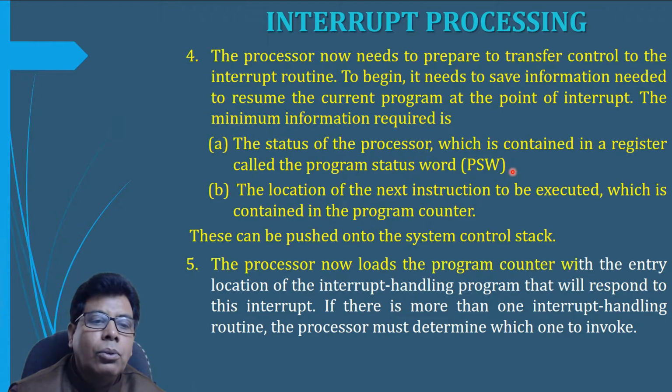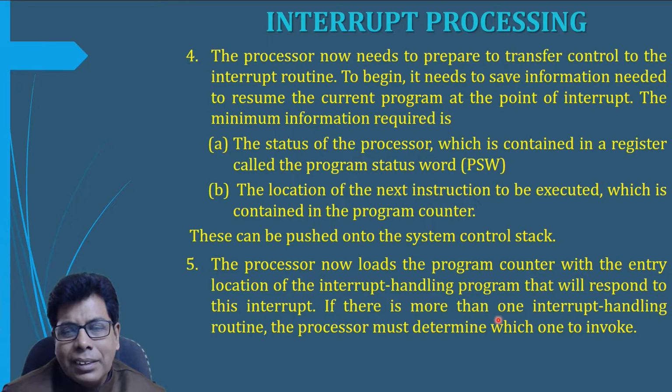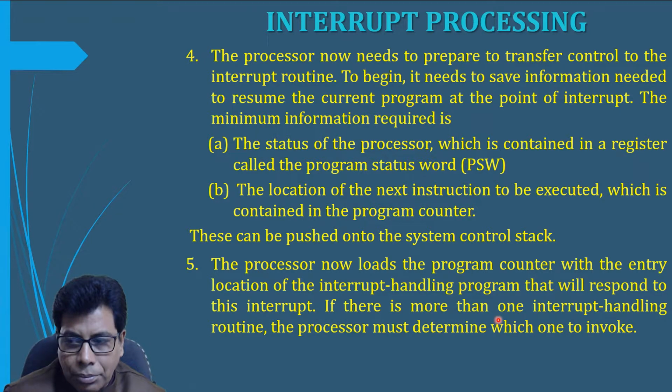Then the processor loads the program counter with the entry location of the interrupt handling program that will respond to this interrupt. If there is more than one interrupt handling routine, the processor must determine which one to invoke. Depending on the architecture and operating system design, there may be a single program, one program for each type of interrupt, or one program for each device and each type of interrupt.